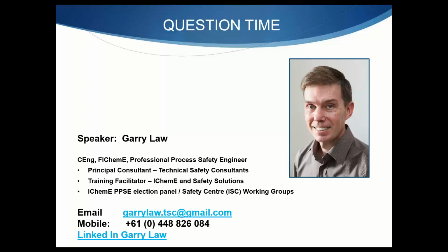Okay. So in that case, the one I was talking about that caused high level by blocking the top nozzle was to do with condensation. The condensation caused a vacuum. So you had vapor in there. It was actually in a tank. It might be completely different because normally tanks are atmospheric temperature, so you may not get that condensation going on. But if you have got some vapor there and it condenses, then it causes a vacuum that sucks the liquid back up from the bottom nozzle, and that's what causes it to show higher level than you would have in the tank. Okay, great.